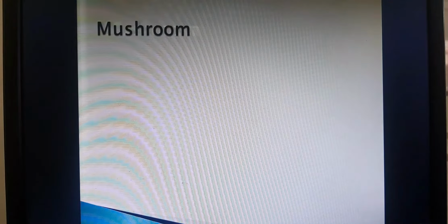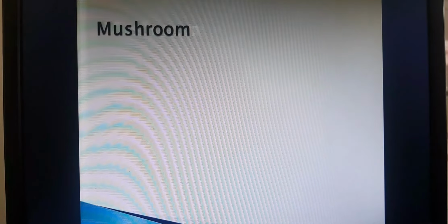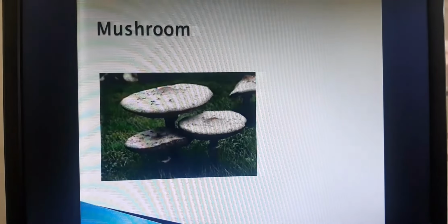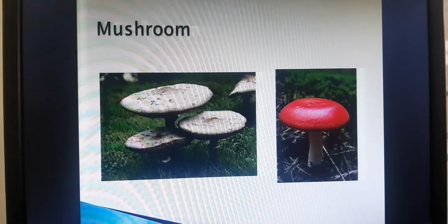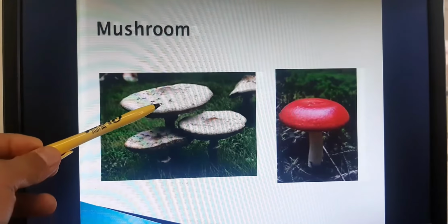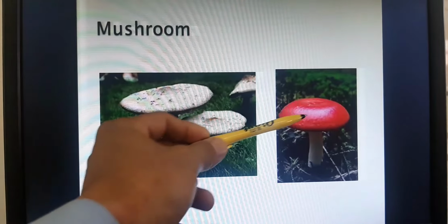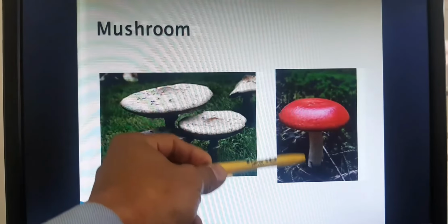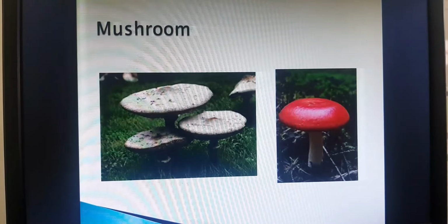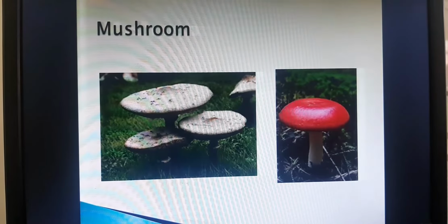Okay, so why is it a mushroom valve? Because it resembles a mushroom. As you see, the mushroom has a head, and it also has a stem. So our valves in the engine are like those of a mushroom. Okay, so here are our valves. The larger one being intake, and usually the intake valve is bigger than the exhaust valve.